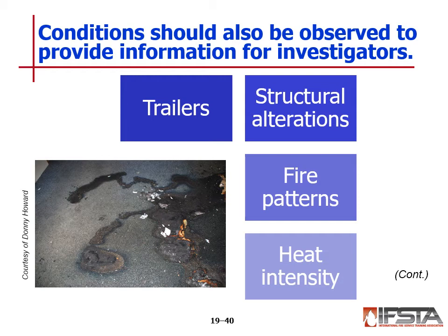Again, when you do a little more homework on melting temperatures, you're not going to be able to remember them all, but if you have an understanding of what temperatures things melt at, that will give you a very quick indication of what the potential temperature was in that fire compartment.